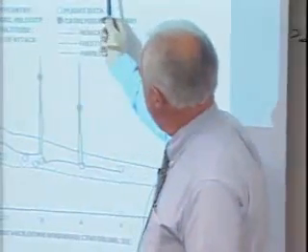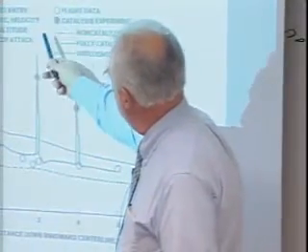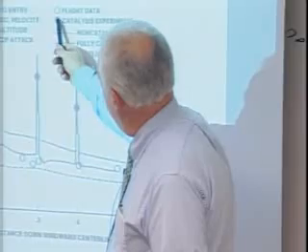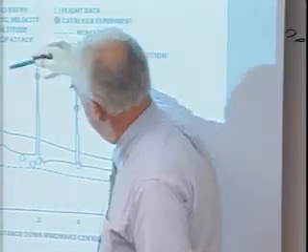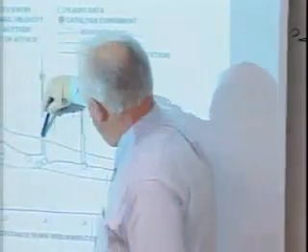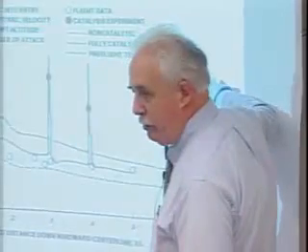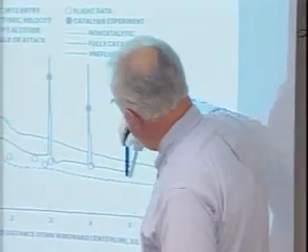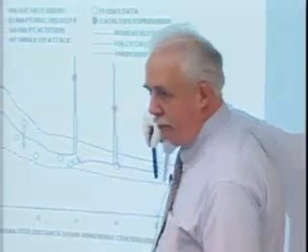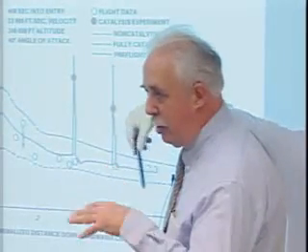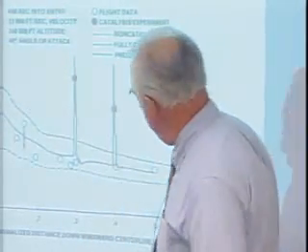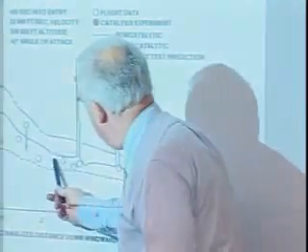And this is surface heat flux at one particular time in the entry. The circles are flight data. These are catalysis experiments. This is a fully catalytic or equilibrium heat transfer. This is a zero catalysis non-equilibrium, boundary layer non-equilibrium. Now the reactions are not occurring in the boundary layer. This is the flight data, the open circles.